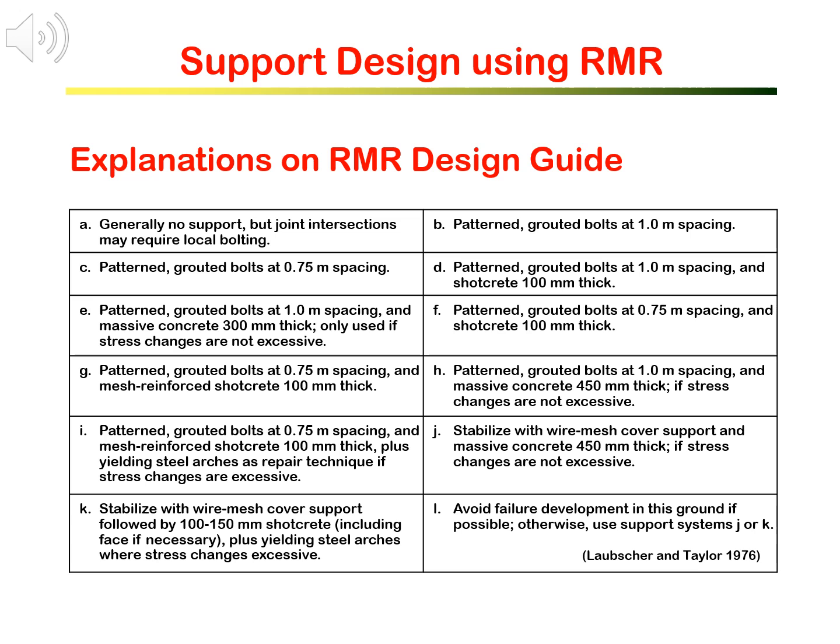Patterned bolts are in fact the same as systematic bolts, with different spacing. Bolts here are fully grouted. You may have noted the use of yielding steel arch when there is excessive stress change.